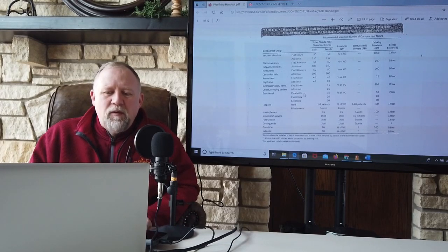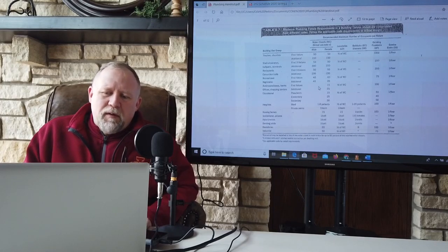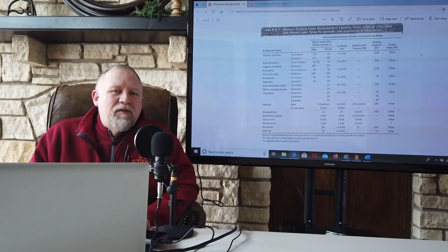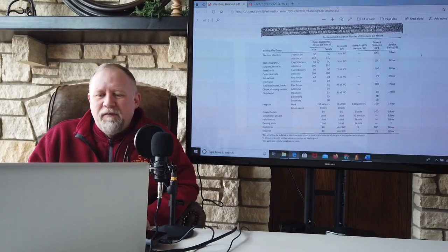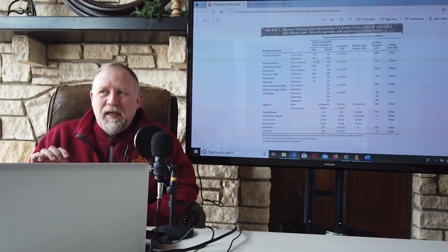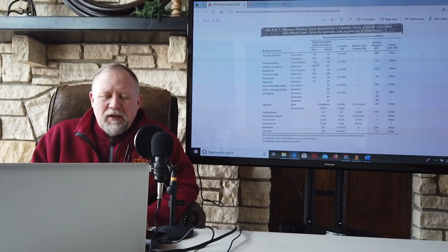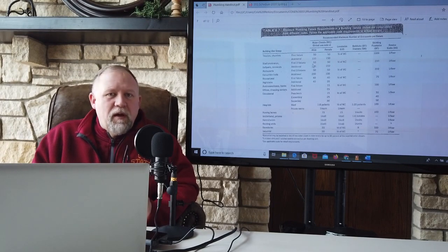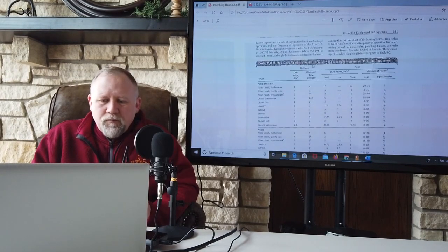What is the building use group? What are they using it for? Remember, very frequently, you'll have a smaller number for the first 50 fixtures, and then after that, one fixture can handle up to 150 people in a theater or a church. And then for offices and schools and stuff, it's different. So take a look at that. So we get our total occupancy, then we get our total number of water fixtures.